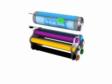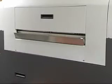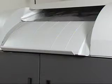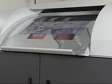Drum rotation speed is adjusted based on the density required for each color separation. Once exposure is complete, the donor releases and is ejected from the back of the approval imager. This cycle is repeated for each color until the full multicolor image is built up on the intermediate material. At this point, the image is reversed on the intermediate and exits the approval imager in the front tray.